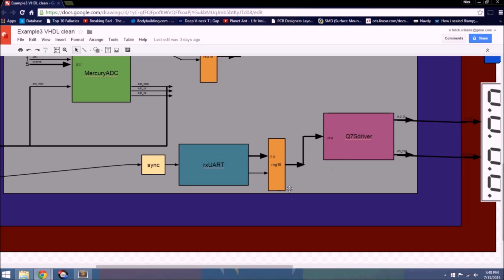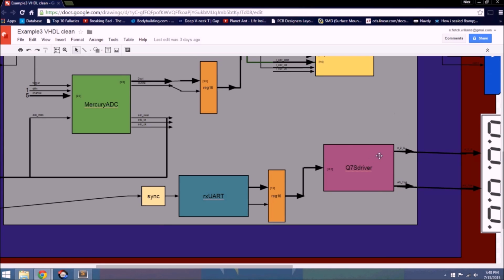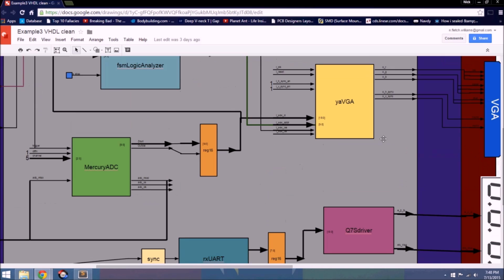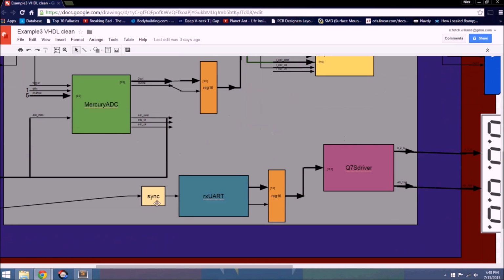As you can see, it's a completely parallel process. The oscilloscope portion functions independently of this UART to 7 segs hardware. This is a powerful characteristic of FPGAs. Microcontrollers have time constraints, whereas FPGAs have spatial constraints, which means there are no nuances whatsoever in adding this additional hardware here. All it means is I'm going to be taking up more space on the FPGA.